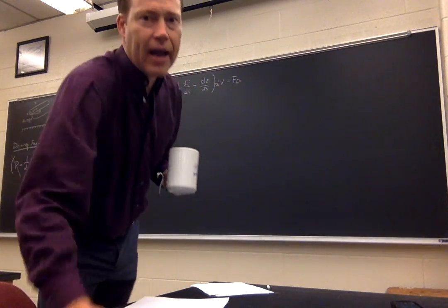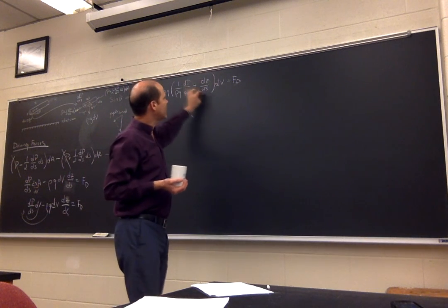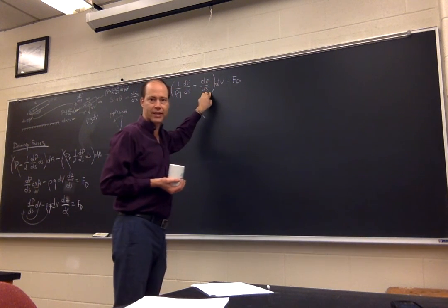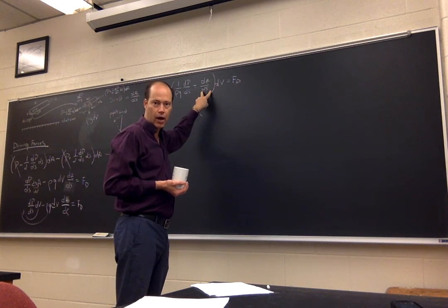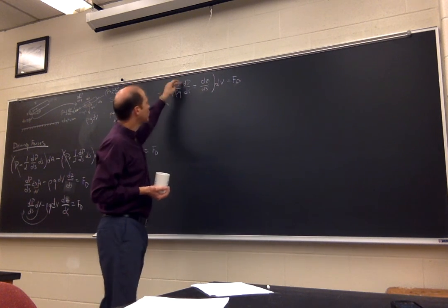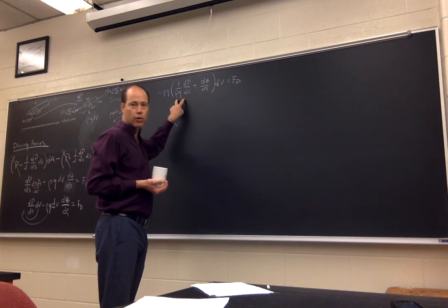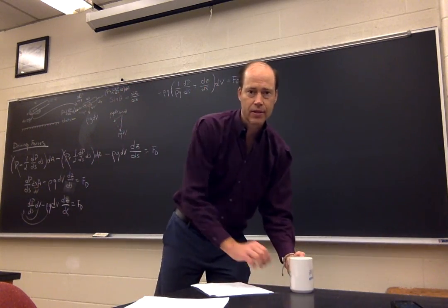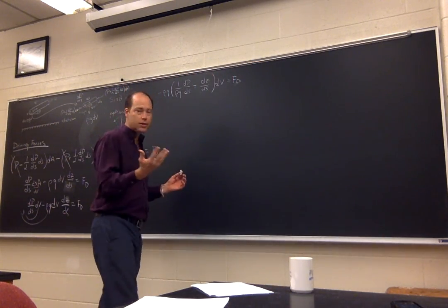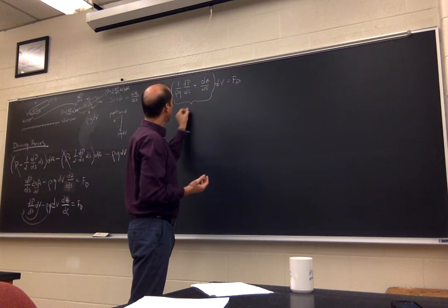Namely, what we're looking at here in the parentheses is the change in elevation over the distance, which is a change in the elevation head of that pipe. And then we're looking at the change in pressure over that distance divided by rho g, which is effectively the pressure head in the system. So the driving forces in this system are the hydraulic head.